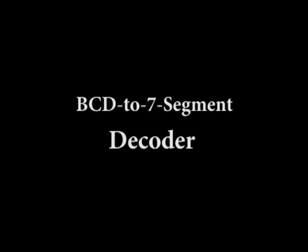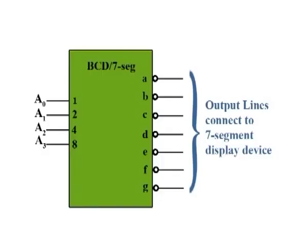The BCD to 7 segment decoder. As shown in the logic diagram, the BCD to 7 segment decoder accepts the BCD code on its input and provides output to drive a 7 segment display device to produce a decimal readout. The 74LS47 is an example of an IC device that decodes a BCD input and drives a 7 segment display.